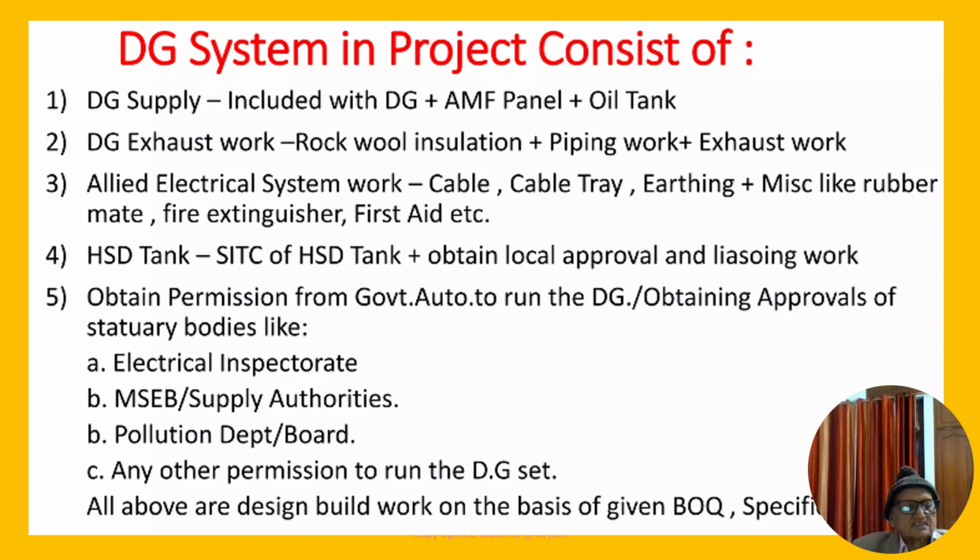Second, DG stack work, with rock wool insulation plus piping work plus exhaust work, as suggested by CPCB, Central Pollution Control Board, and their agencies in different states. Third, allied electrical system work. You have to design cable tray, earthing, plus rubber mats, fire extinguisher, first aid devices, etc.